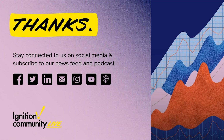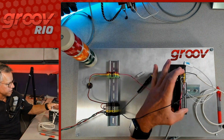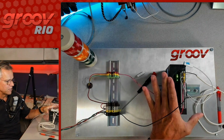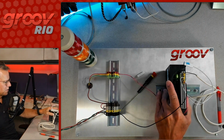This one's fantastic. Do we need different modules for the different sensor signals, like 4 to 20, 0 to 10, or thermocouple? And of course, the answer is no. That's the beauty of Rio, is all those configuration options are around 60,000 permutations. Yeah, indeed, you're right, Ben. From one single module, we can software configure any of these channels for those various points that I did through the web browser. So there is only one part number, and you only have to stock one. So imagine how many spares you can eliminate with this type of configuration.